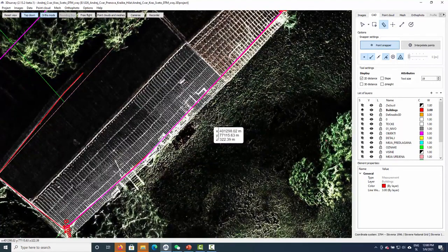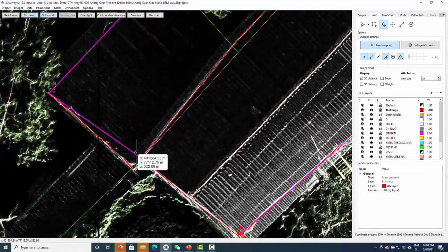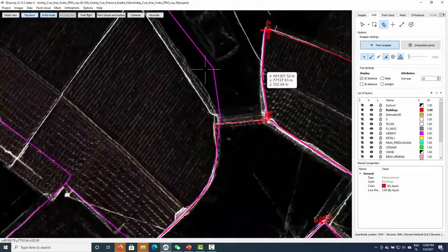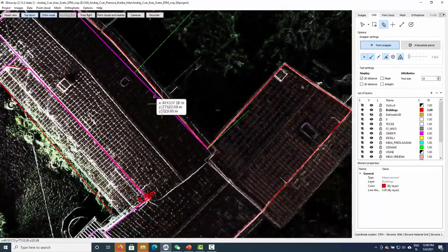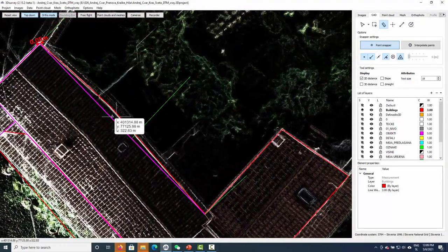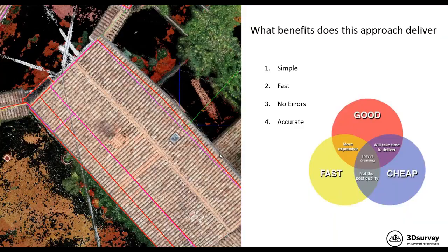So in short, what we should take away from this is that the accuracy we can achieve from measuring the building corners with this technology will probably be just as good as with the total station, with the added benefit that the measurement is faster and we are not making so many gross errors, like for example this one here, this one back here, or this one here. Here a point was measured at the front, a point was measured at the back, and the wall was connected with a straight line, but the wall will not always be straight, so we might make this kind of error.